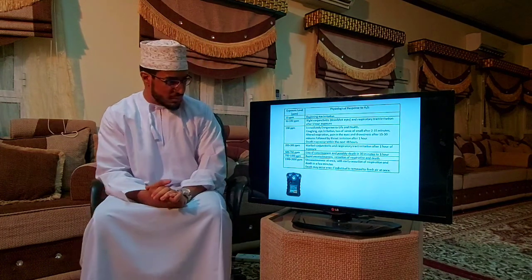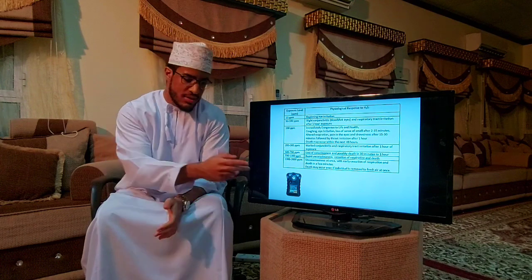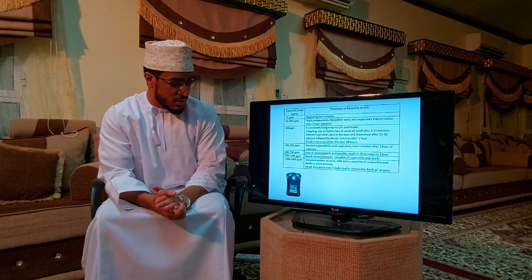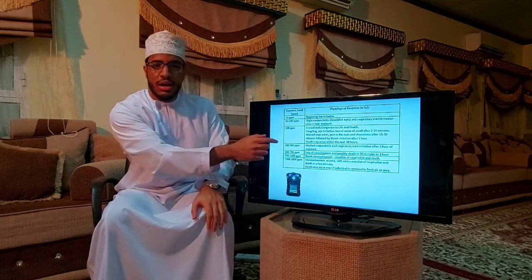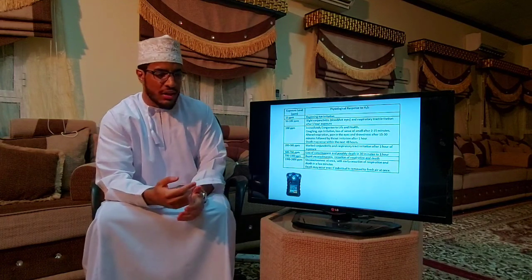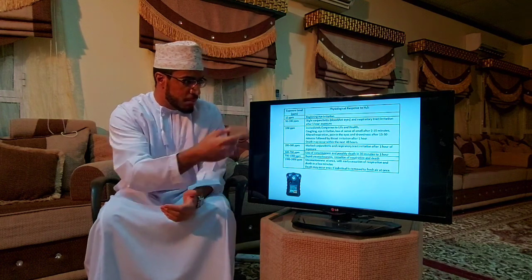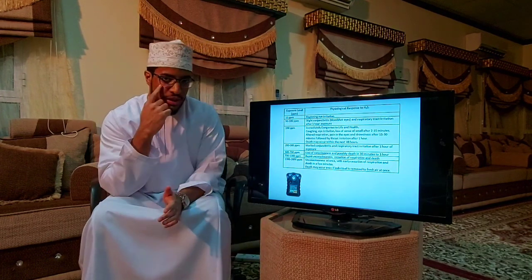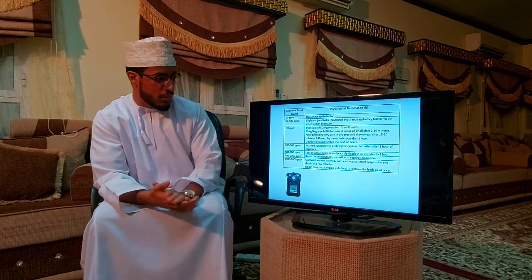ppm means parts per million, and as you can see, this is a device that is used to measure H2S in ppm. Each ppm level has a meaning and a hazard. At the beginning, you can see eye irritation at 10 ppm, but when it increases to between 50 and 100, you get bloodshot eyes, a lot of chest pain, and breathing problems.